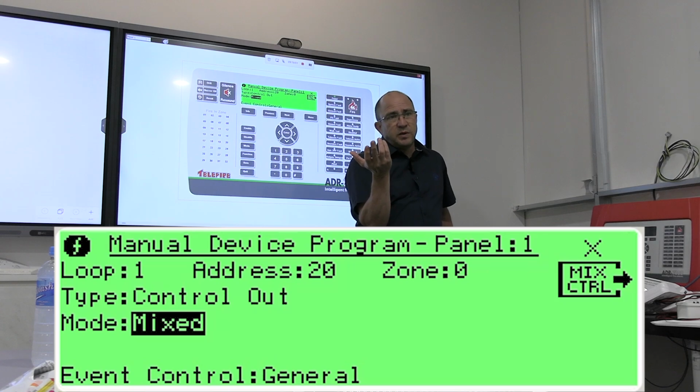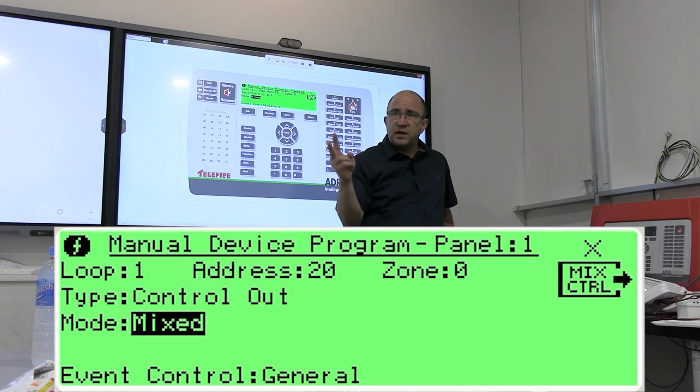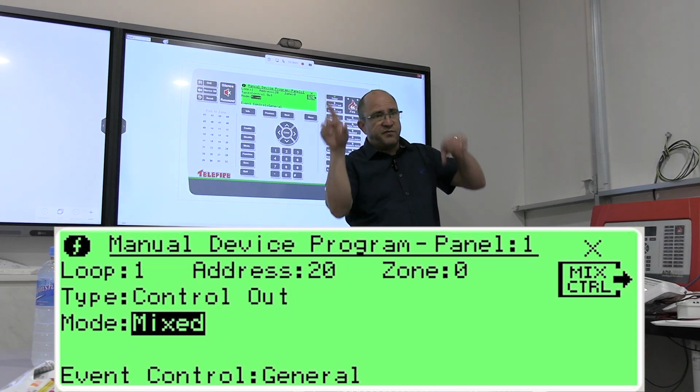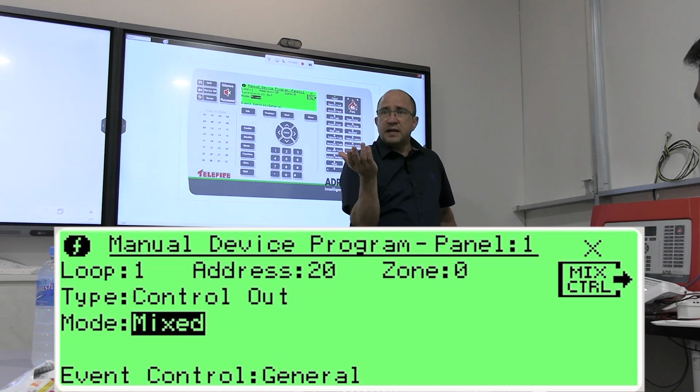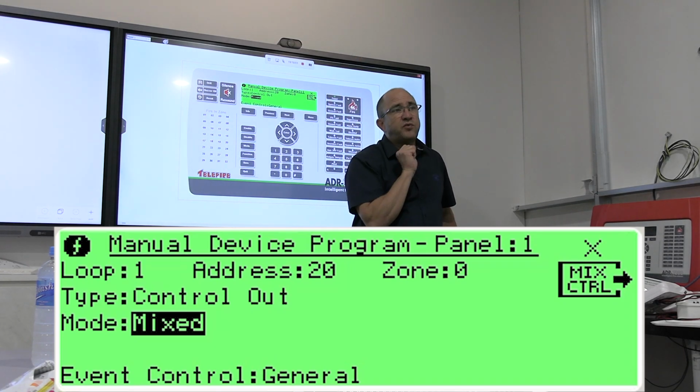So I told him, what's the problem? I'll take the dry contact from that Wi-Fi machine that the government gave for earthquakes, I'll connect it to an input device that will create an alarm. I'll do it in alarm matrix. In other words, 2 or 3 alarms, I don't care. And then the doors will open.